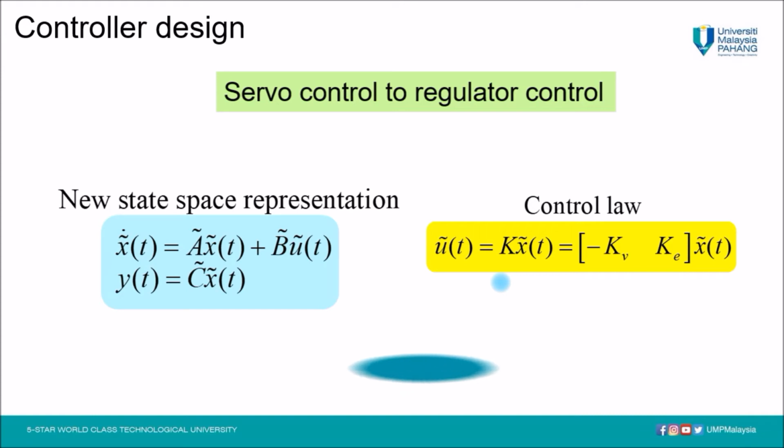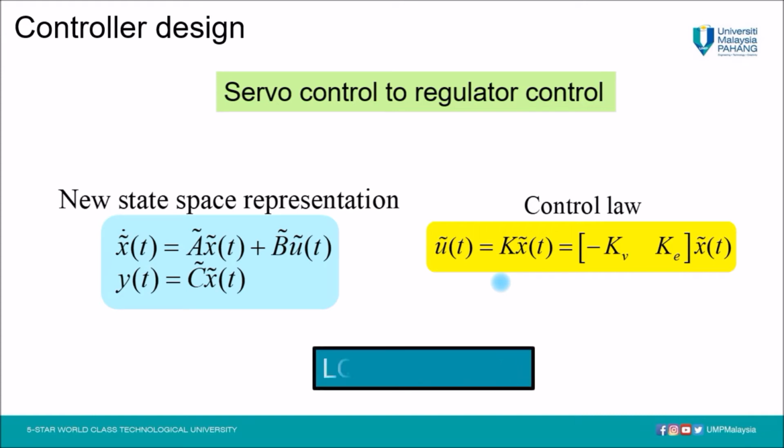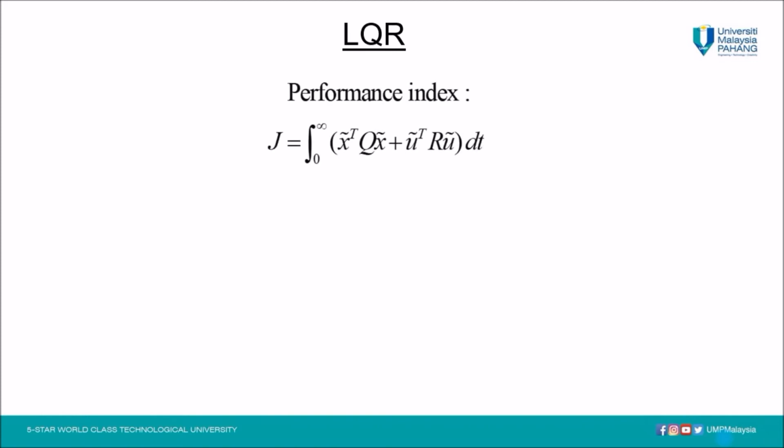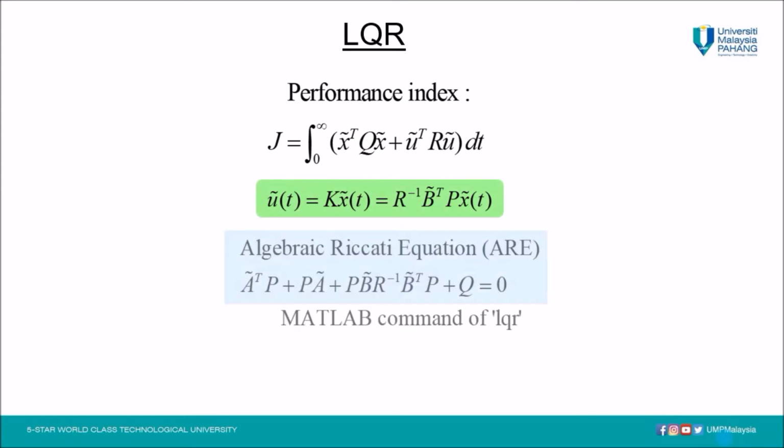In this study, we compare the proposed technique LQR-LMI with regular LQR. First, we implement regular LQR, which needs to obtain the optimal solution that minimizes the performance index of J. We use this related control action to minimize the performance index, where the optimal matrix can be solved by computing the algebraic Riccati equation with the command of LQR in MATLAB simulation software. The minimum condition can be defined as this condition.